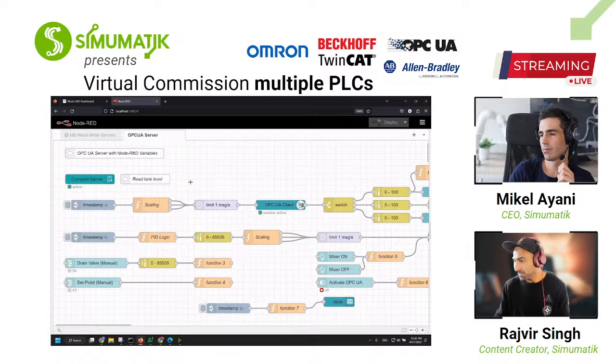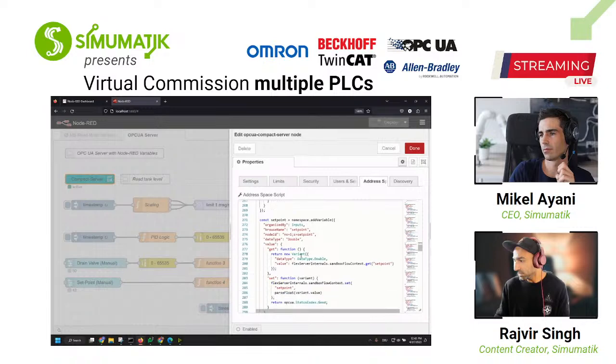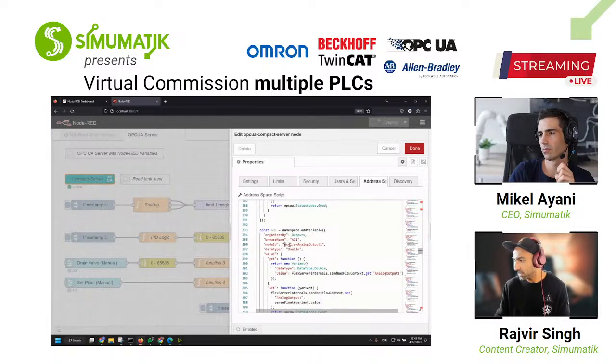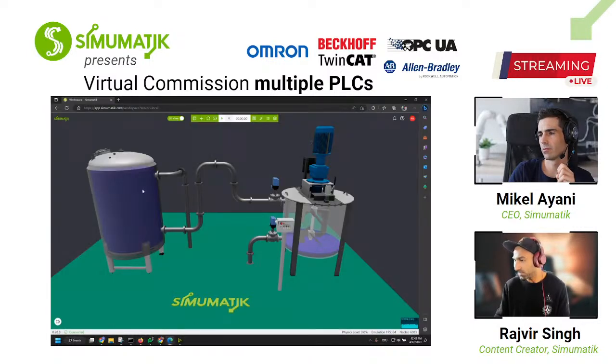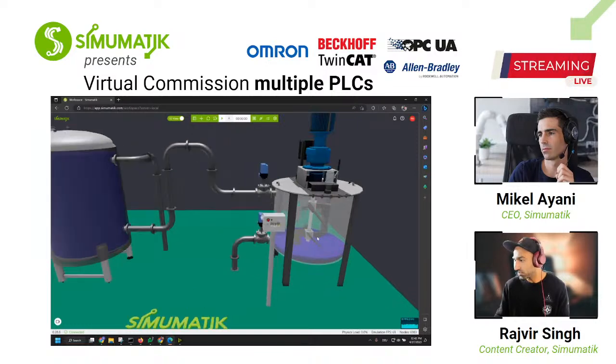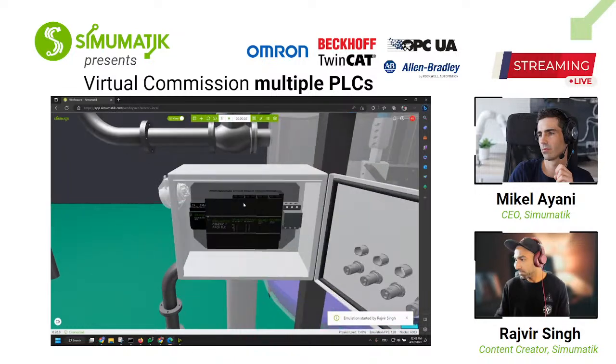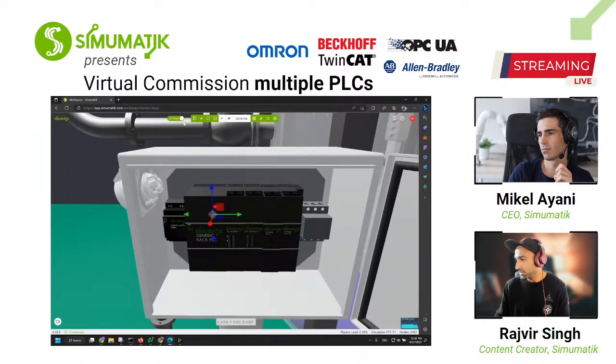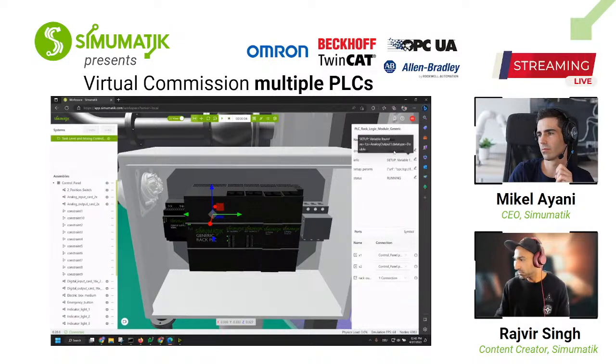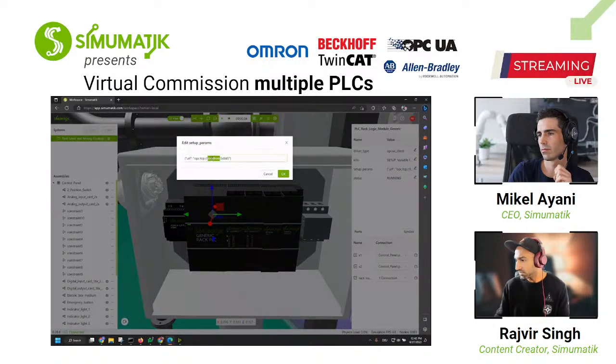All right, so once you define the address space here, these node IDs, I am entering them in my PLC. I can show you now. Here, if I press play and open this, I have the same PLC inside, but this time this PLC has an OPC client. And here you can see the IP address, which is localhost, so that's running on the computer. I would enter localhost, and this is the port of my OPC UA.